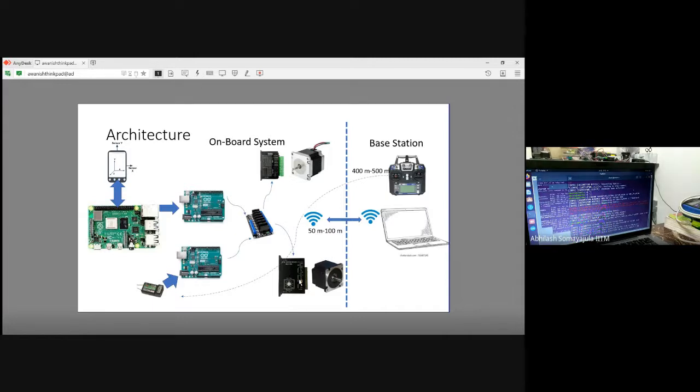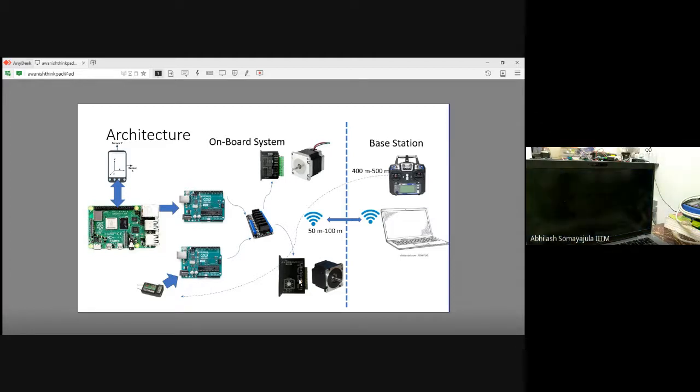But here we have feedback and we need it, because we are not running at high RPM. Our application is low RPM and high torque. So we are not providing three-phase current to the motor directly; we are providing a direct DC voltage. The drive is making it into a three-phase current system, such that one coil after the other, the electromagnetic coils, gets activated so that the motor rotates continuously.